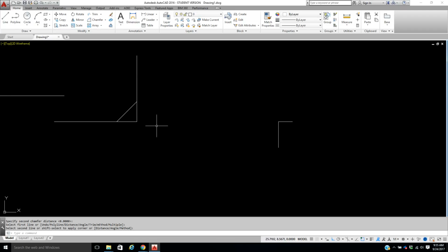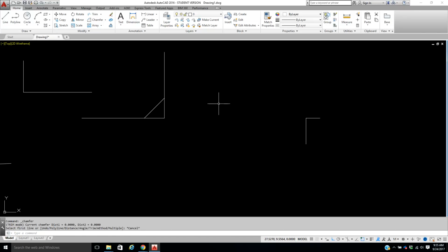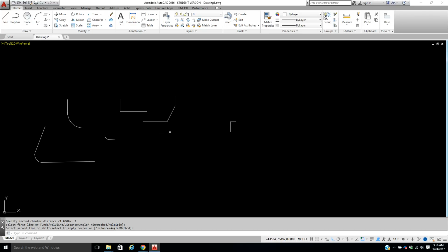So I'm not going to go too much into the chamfer. It's not that we use it that often, but you can use it as angles, things like that. You can do chamfers such as, let's erase this one here. We can do something as a chamfer with a distance. Let's go 1 inch in one direction and 2 inches in the other direction. See that? So this way went 1 inch, this way went 2 inch. This is good when we're working mechanical and they're asking for a nut or a bolt and they tell you there's a chamfer there. So that's what the deal is with chamfers.